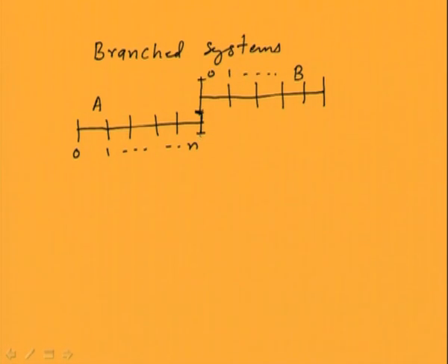Then there is another branch which is coming out from the same gear, let us say branch C. So what is happening, we have a branch A from where power is going to branch B, and also to branch C. Now our aim is to find out how we can get the natural frequency of this system, so that we will know whether we can avoid resonance conditions in this particular system.